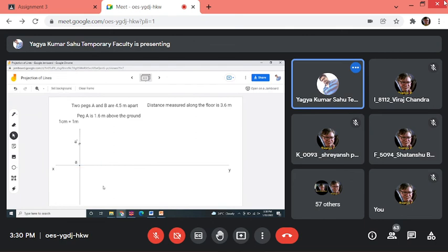On the XY line. 1.6 centimeters. What 1.6 centimeter? Small a dash 1.6 centimeter, right? Yes, sir. Above XY. So we located A dash. Where will we locate A? On the XY line, because it is lying on the vertical plane. Is it? So I am writing 16, because all dimensions are in millimeter.